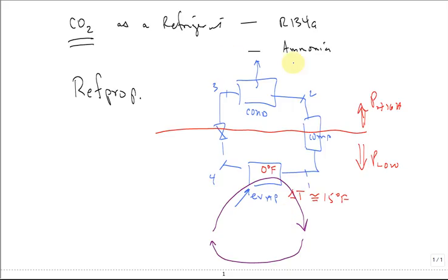Out here, we have some other air coming across, and it's up on the roof, the condensing unit, and it's a hot day, and you still want to have ice cream or ice inside your warehouse. You have to reject heat to, I don't know, 125 degree F air. Not room, but it's maybe rooftop. The temperature that this condenser is going to work at, if you have a delta T of about 15 degrees F in here, is the refrigerant in the condenser has to be higher. So it has to be 100, 140. So if your refrigerant is 140 or greater, it'll push the heat out and make the hot air outside on the roof even hotter. So you kind of get a sense of these real delta T's that exist to make the heat transfer occur. Let's jump into here now.